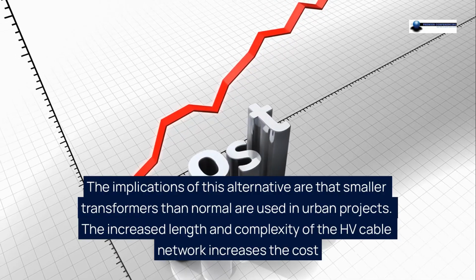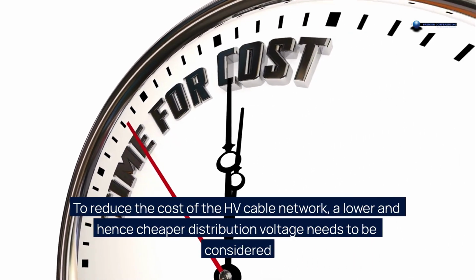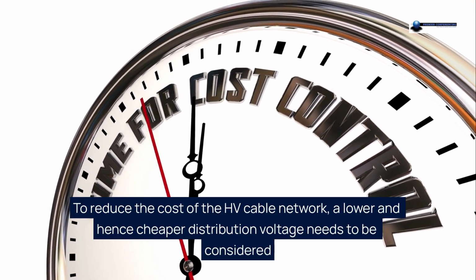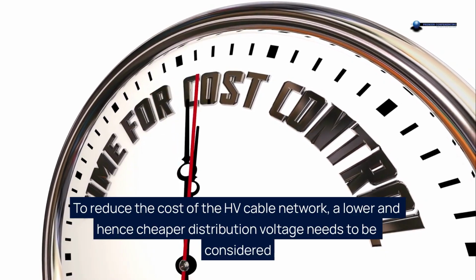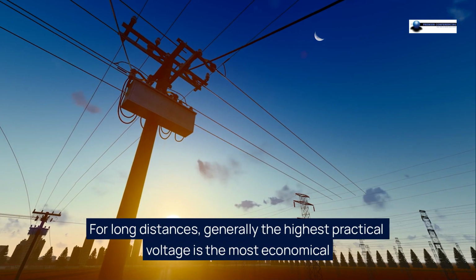The increased length and complexity of the HV cable network increases the cost. To reduce the cost of the HV cable network, a lower and hence cheaper distribution voltage needs to be considered. For long distances, generally the highest practical voltage is the most economical.